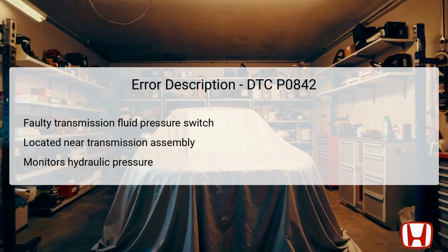If the switch fails or experiences electrical shorting, it may cause the system to remain stuck in the on position, impacting gear shifting behavior. Notably, it's important to recognize that this error is not a result of mechanical transmission failures, but strictly relates to electrical circuit issues. Addressing this code early on is paramount to prevent extended transmission issues.